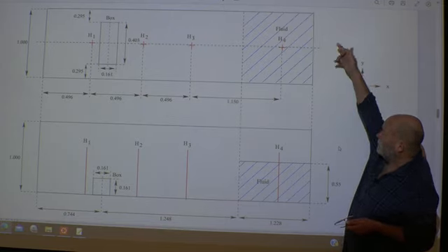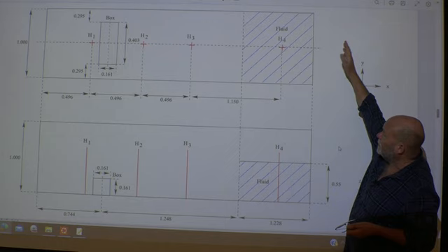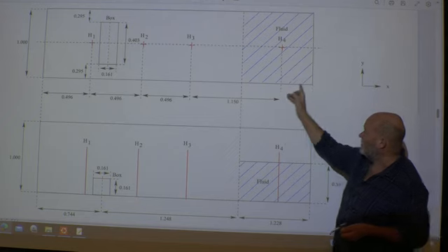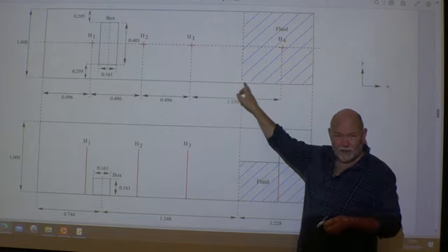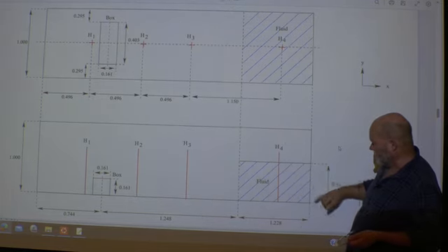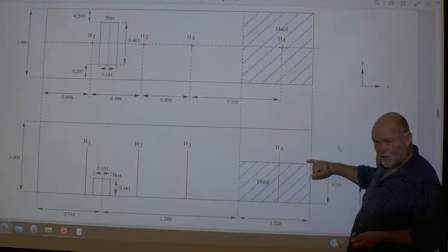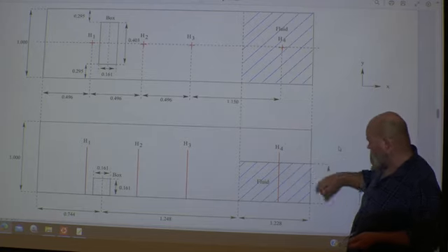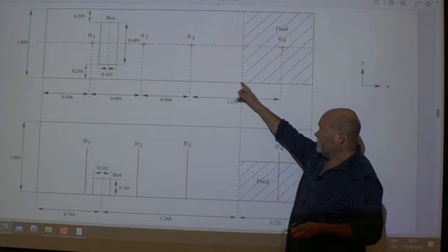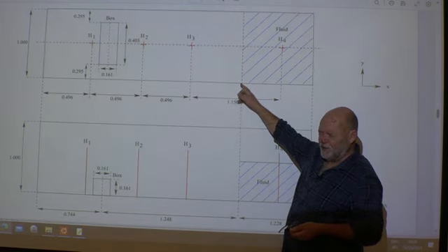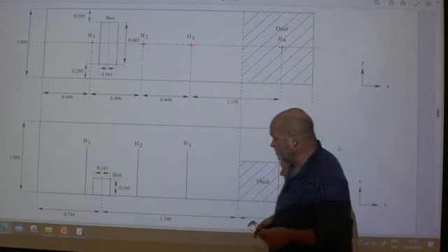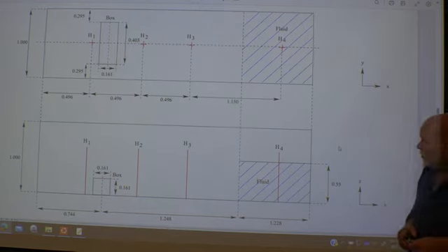For the, what's it called? I think it's the Y direction here. Of course, it goes from wall to wall, so that's not a problem. But this distance should hit a cell face somewhere here. And also the height in the Z direction here should hit a cell face close to this value, 0.55 here. And I think this one was 1.992 meters or something like that from the left side. Okay.